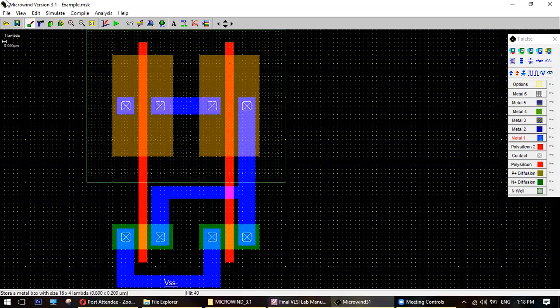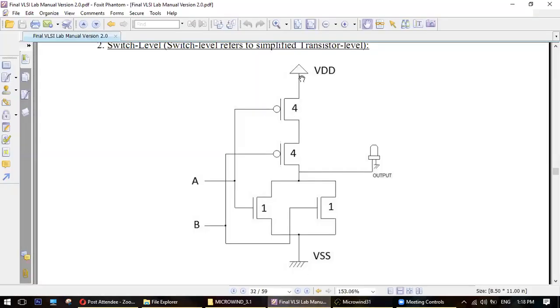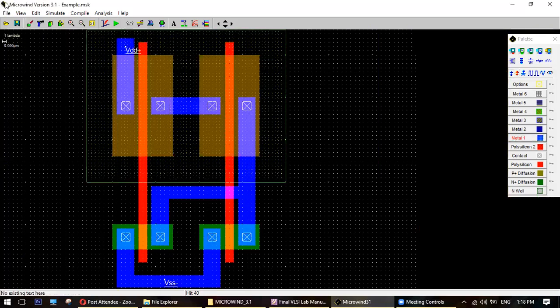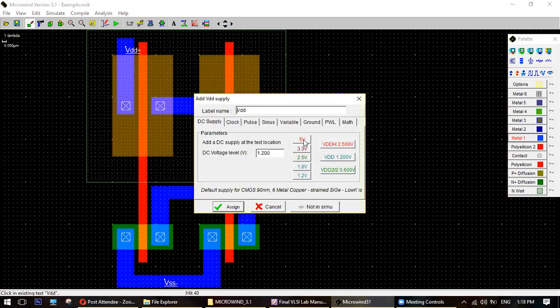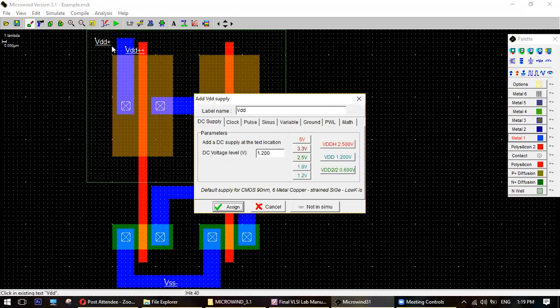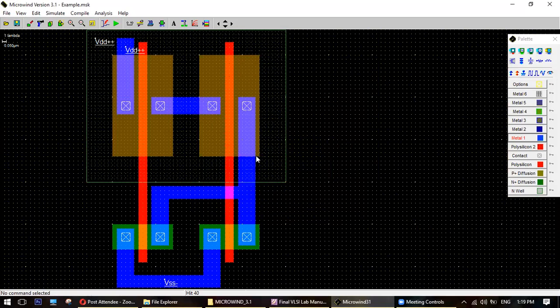Now, next, our A source will be connected to the VDD. So let's take it like that and connect the VDD here. It will be 5 volt. Connect an extra VDD here as well. It will be 5 volt. Understood, everyone? Now connect the inputs.